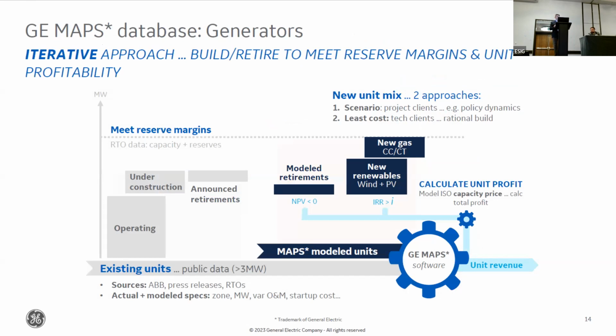We do incorporate some capacity expansions, and it's more through a process, and I think we primarily use Python for this, particularly in the later portions of the forecast, where the model is showing that there's not enough reserve margin being met in the different markets. So we will add a layer of either new gas turbines or additional wind and solar, and particularly for wind and solar, if there's a planned target for a particular state, we'll incorporate that.